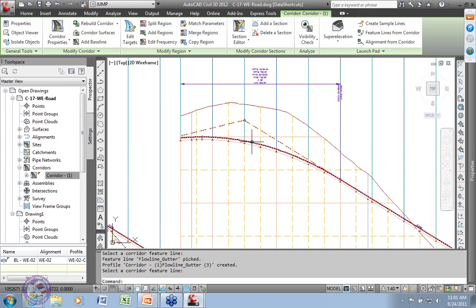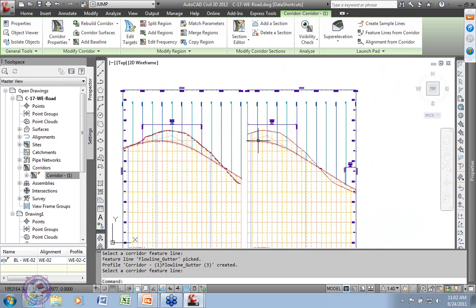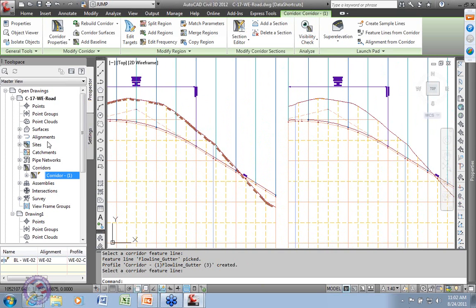So if I have a different centerline alignment, for perhaps the edge of a median I want to show, or a ditch that's independent of my roadway cross section that I want to define, I may want to superimpose that profile. You would create a profile view, grab it, and make a copy of it over here. So that's a different thing.